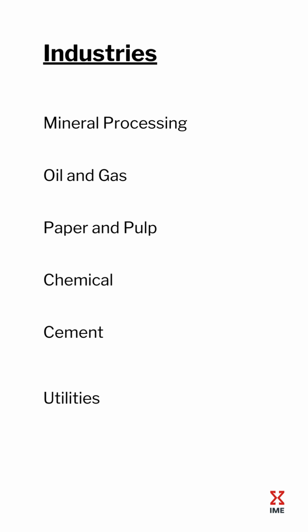For example, they were able to detect the early warning signs of a gearbox failure just by analyzing that time and state data. It even picked up on an instrument measurement that was drifting, something that had gone unnoticed by the control system and maintenance personnel. Wow, talk about preventing a potentially major disruption. It's almost like having an early warning system for the plant. That's a great way to put it. That's the kind of proactive capability that time and state enables.